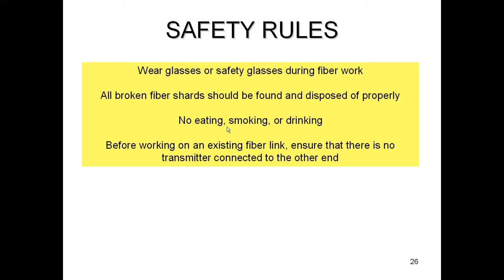Now, what are the safety rules? You need to remember the safety rules for fiber optics because it's very important. When you are preparing a fiber end to be terminated, you have to strip the fiber, and you use a special stripping tool. This is important. You must have the proper tools to work with fiber optics. So you're going to use a stripping tool. In the process of stripping off the outer jacket and the inner jacket, there's always the possibility you're going to break the fiber, and you end up with these little inch-long or half-inch-long pieces of fiber.